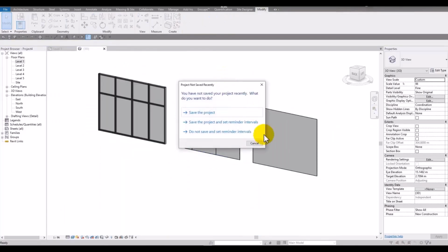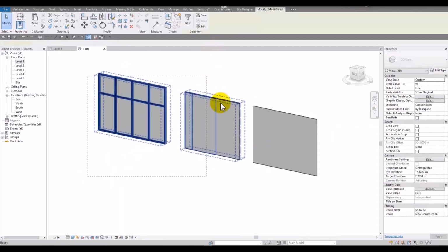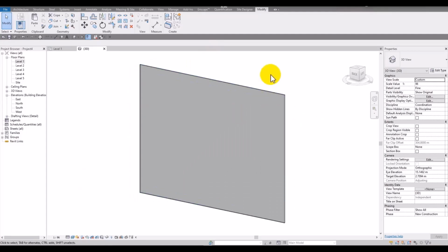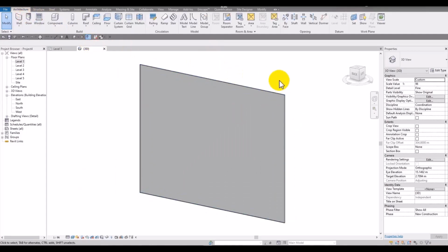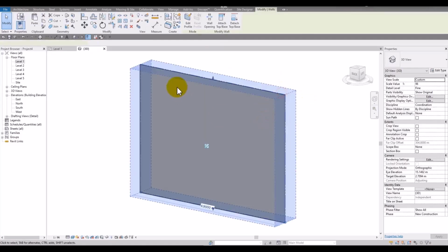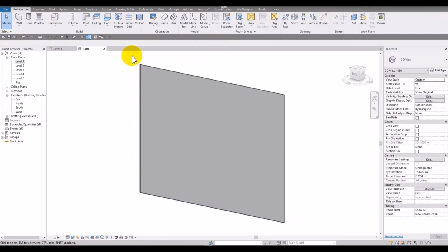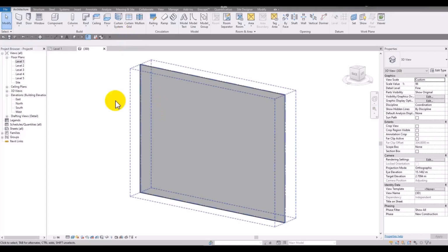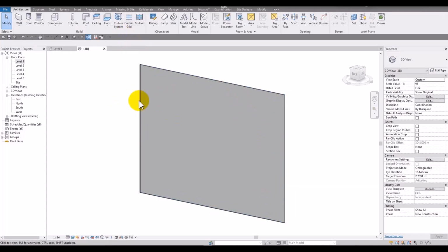See, a complete curtain wall consists of some components. The first one is the curtain wall. Another one is the grid. Grids can show the divisions on the window, which you can have right here manually, or you can have them from the settings, defined with special, equal distances. Or we can have them like this, simple.